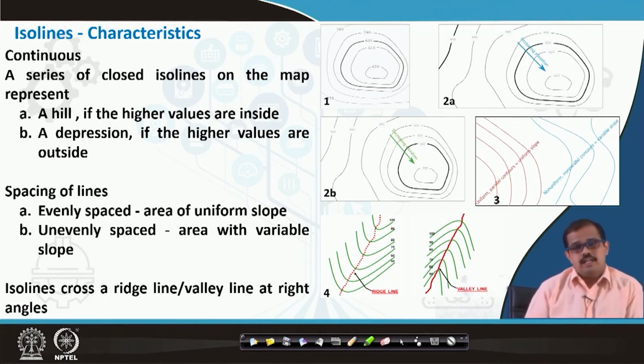If you start drawing lines at a 20 feet interval as I have shown previously, and suddenly you start looking at values at 40 feet and then 60 feet, then it is not a true representation of the particular surface. That has to be characterized at 20 feet all throughout the model.